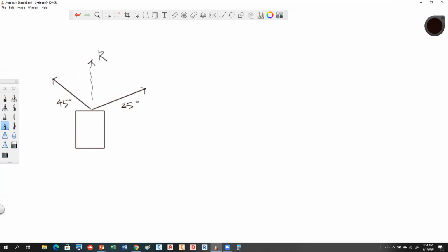We're going to have a chain here and a chain here. This chain will be 100 pounds, and this chain we don't know. So what we're going to want to solve is the amount of pull in this chain here when we're pulling at 100 here at 45 and keeping this at 25. So once we get this thing going, it's going to go straight. So we're going to neglect the weight of the car, and we're going to say it's a frictionless surface. So what we're going to do is come over, and I'm going to solve this with triangle tip-to-tail method.